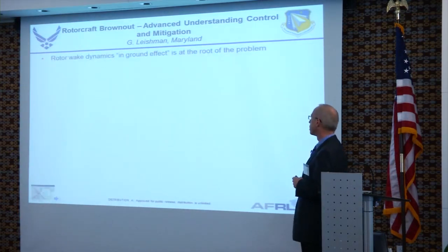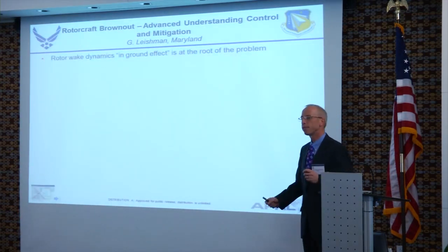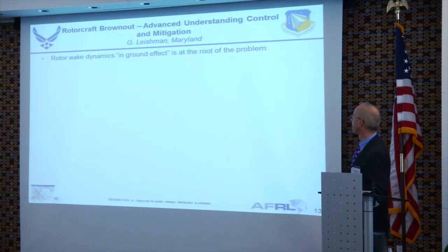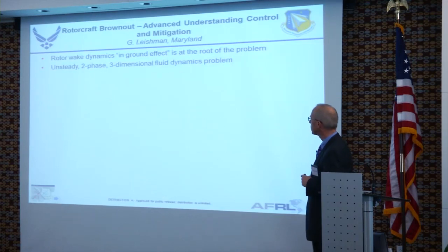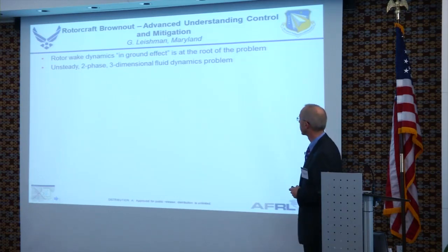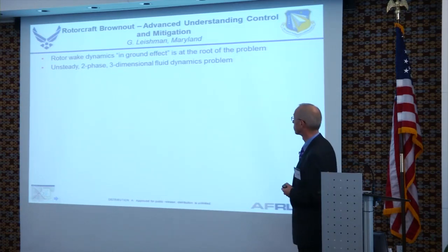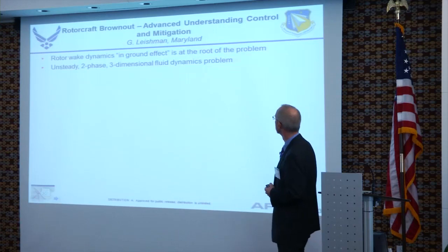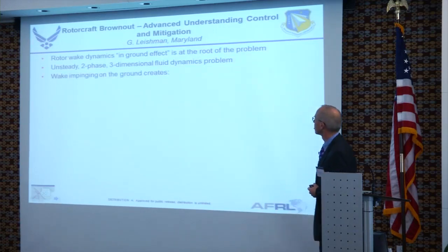Well, this is a rotor wake. Really, the driver here is a rotor wake in ground effect problem. This is really at the root of what's going on here. It's an unsteady, two-phase, three-dimensional fluid dynamics problem. So unless you have combustion going on, this is about as hard as it gets. And I don't know why you would introduce combustion to a problem like this because it's tough enough as it is. But some people forge ahead in any event.